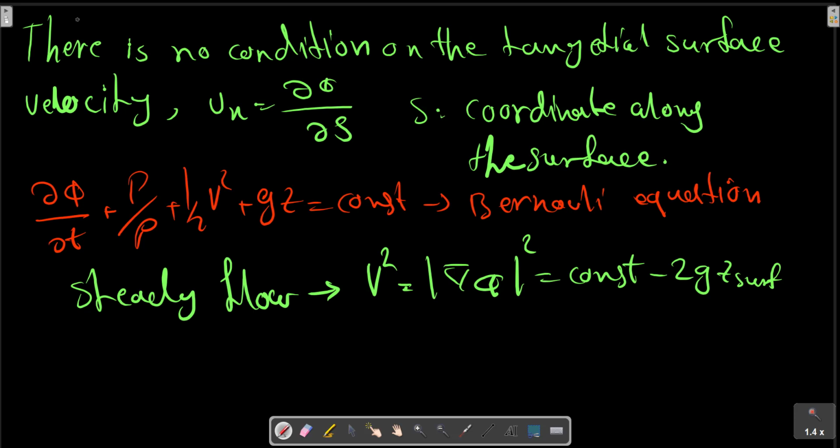There are many analytical techniques, including superposition of elementary functions, conformal mapping, and numerical finite difference, numerical finite element, numerical boundary elements, and electric or mechanical analysis that are now outdated. Having found the velocity potential from such analysis, we then can compute the velocity vector V.